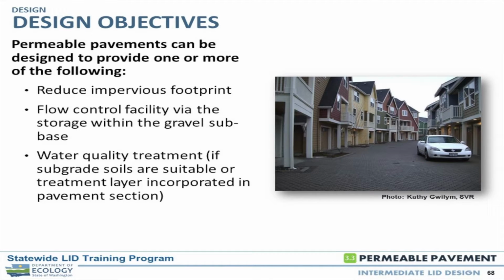And so while the pavement section itself is not considered a water quality BMP, it can meet water quality objectives by infiltrating into the soil below. So if the soil below the facility meets the criteria for separation and for cation exchange capacity, then it can meet your treatment requirements.